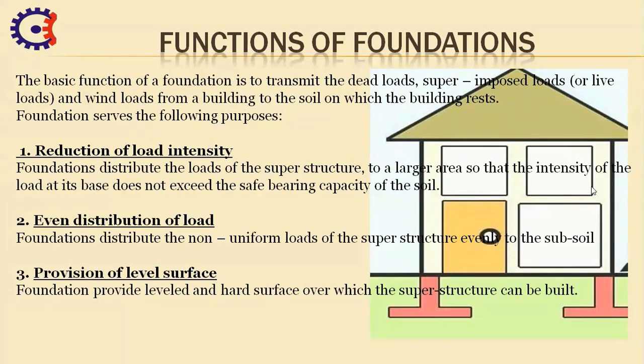So the basic function of a foundation is to transmit the dead load, superimposed or live loads and wind loads from a building to the soil on which the building rests. The following are the six purposes which are required. First one is reduction of load intensity. Foundations distribute the load of the superstructure to a larger area so that the intensity of the load at its base does not exceed the safe bearing capacity of soil. As we know, safe bearing capacity is the most important consideration before constructing any structure.